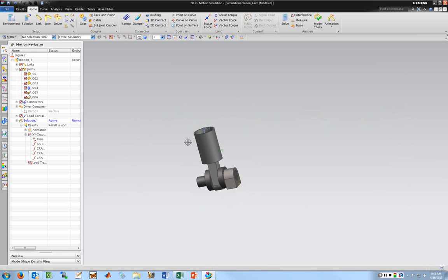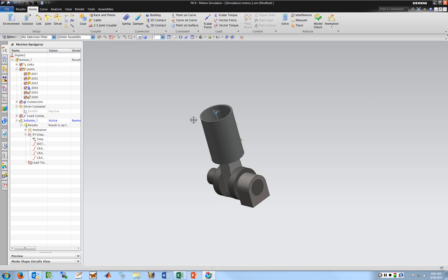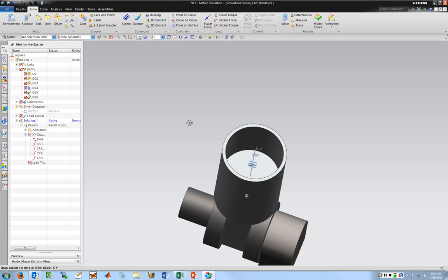So obviously this is incredibly powerful. If you're designing an engine like this, you could use this to help with balancing. If you had accurate numbers for the forcing functions on it, and you're just doing it with air in it, you'd have to model the air spring effect, and also the damping from that as well, because it's never going to be adiabatic.